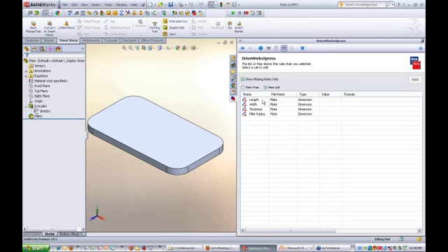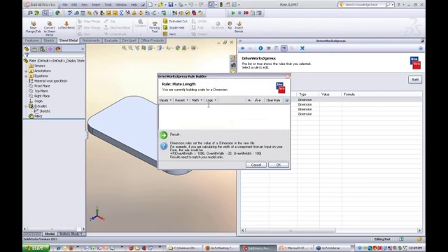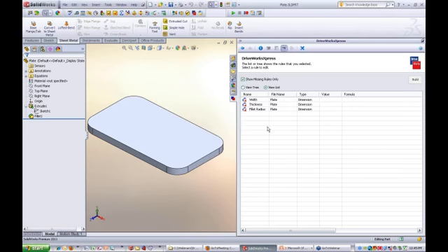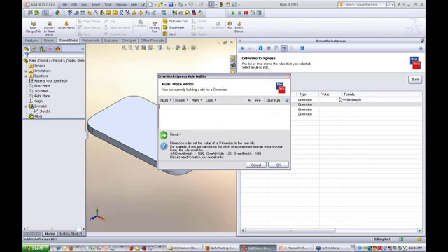So the length dimension that we captured has to be driven somehow, and that's driven by the plate length that we enter into the form. So if I choose that and build that rule, the length dimension is simply controlled by the plate length. Simple as that. I'll turn them all on so you can see them. So the length dimension is driven by the value we put in the form. Likewise for the width, I build the width. And that's equal to the plate width that we enter in the form.